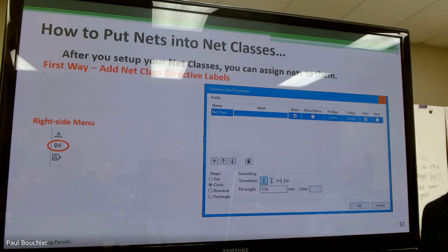Now, I want you to go and find one of the global labels. I think I used global labels on all of the I2C buses, but I want you to go ahead and grab one of the global SDA lines and pull it over a little bit so that there's a wire. Okay, so you can see a little bit of wire.